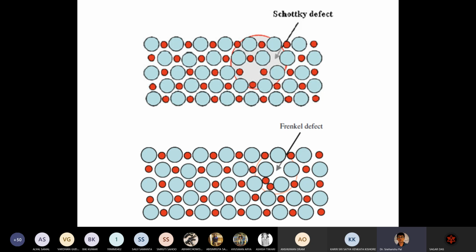However, if we discuss point defects and the influence on the diffusion of components, intrinsic thermal defects can be created in different ways. Suppose for a hypothetical compound, when an equal number of anion and cation vacancies are created, then that is a Schottky defect. And you can see in the picture, ions leave their position, travel to the surface, leaving behind vacant sites. Therefore, such a defect creates volume expansion, leading to a decrease in crystal density.